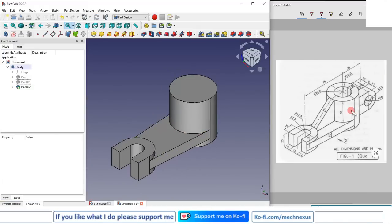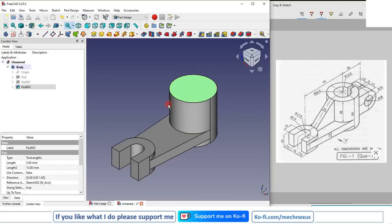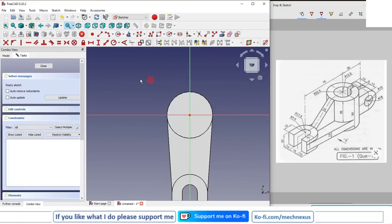and now we will create this feature. So this is on the curve profile. The best way to do it is to select the face and create a sketch, project this arc, and this is 13 plus 13 plus 5, so 13, 13, 26, plus 5, 31.